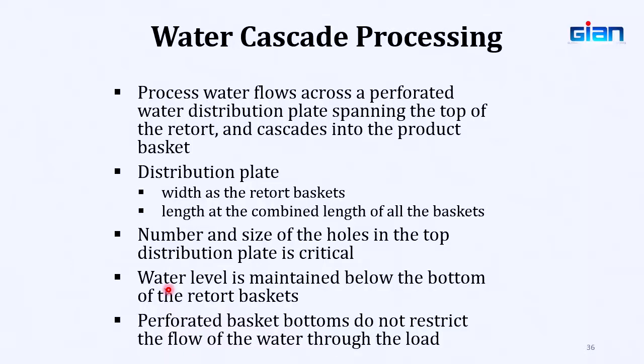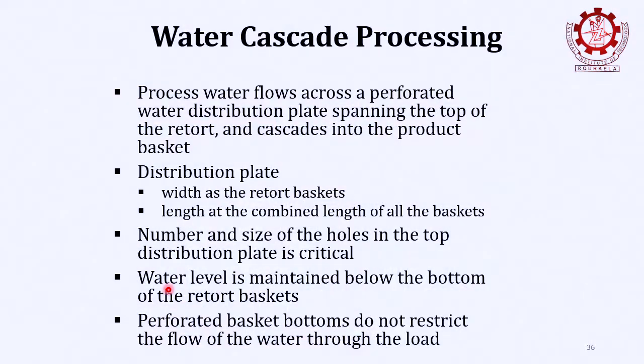So depending upon the can size, how big your retort is, of course you want to design it in a manner such that almost all cans are exposed to this trickling down water, because if any can is not exposed, then it will not be sterilized and you will have a problem. So you want to make sure that all cans are exposed to this hot water and there is no dead spot within that geometry where a can is not being heated.